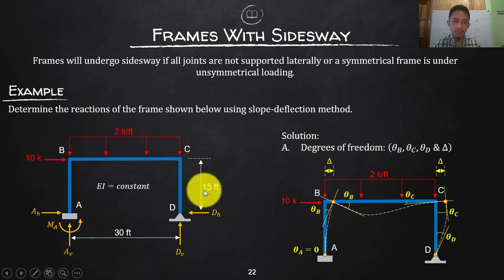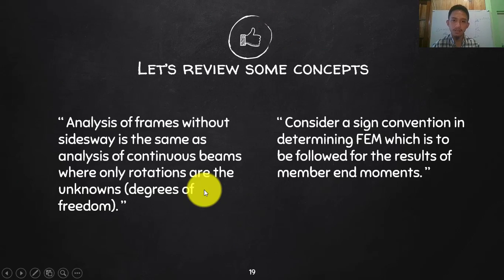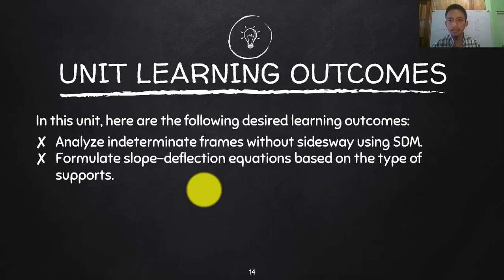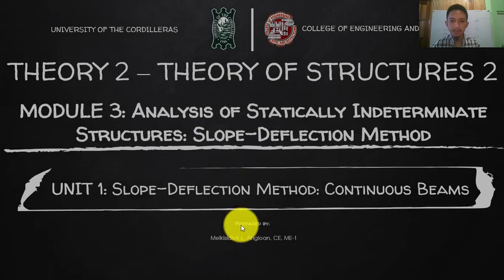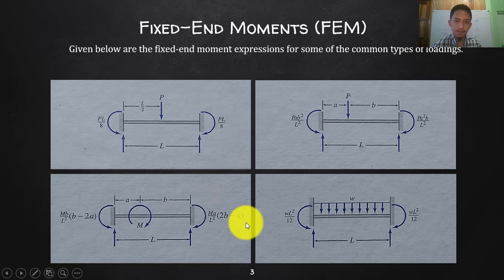Even if you try, let's say, go back to your formulas of fixed end moments, and say this is the case, that the load is exactly at the very end, then your value for A is 0. So even if you have values for P and B, your values of fixed end moments, if A is 0 or B is 0, then all will be 0.